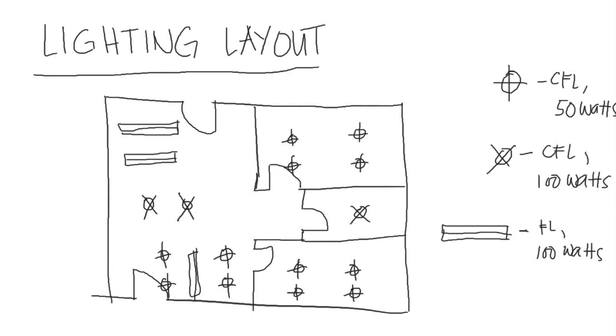Okay, so I've already put the lamps that I will be using in this area, in this floor plan. Next is, you should identify the switches to be used. So in this room 1, I will be using a 2-gang single switch, meaning it is S2. And to connect the lines from lamps to switch, you should use broken lines.